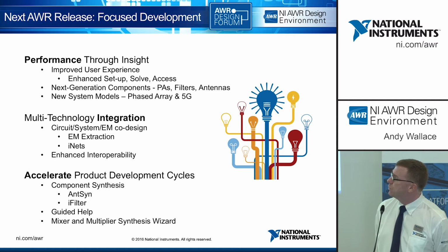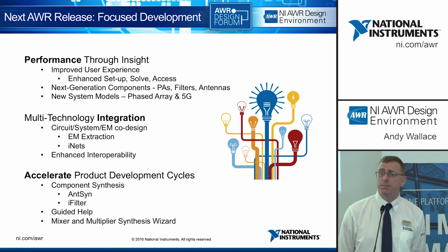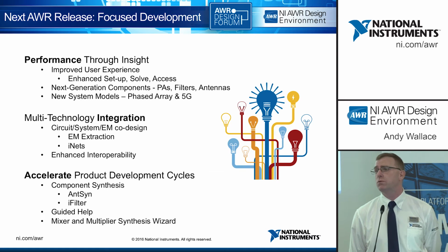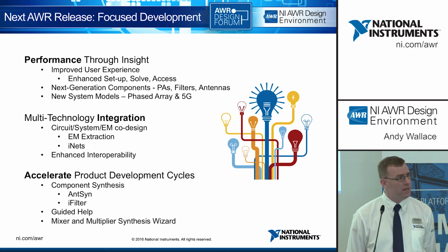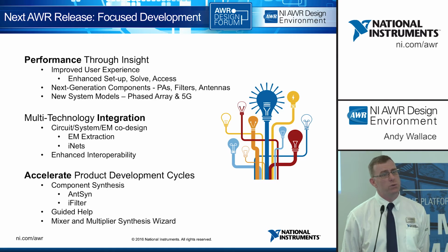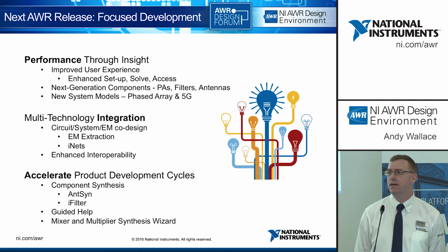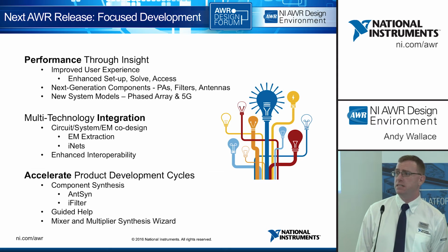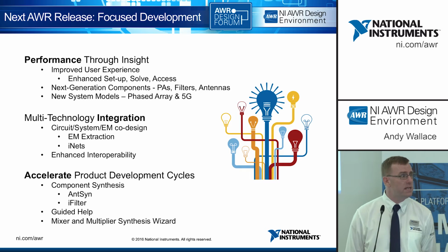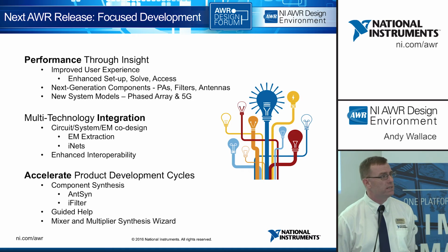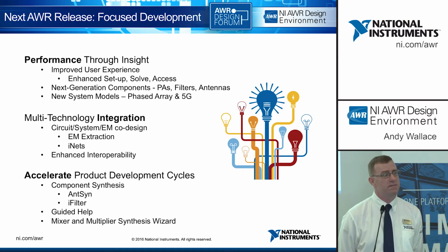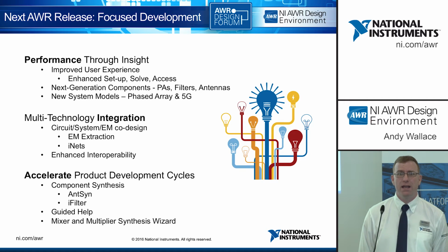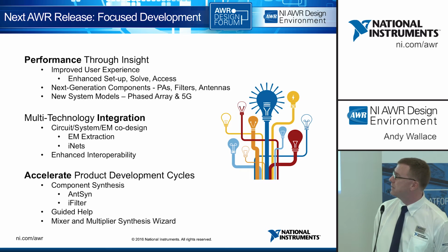Product development cycles, what else have we done? I spoke briefly about Antsyn, but another thing we've evolved is the iFilter tool, a filter synthesis suite that we've had before, and we could do standard filter implementations. But rather than designing the filters, this is synthesis, actually placing zeros at DC, infinite or finite zeros in the transmission characteristics, and synthesizing the filter from there. And again, like the antenna design, that exports into Microwave Office and allows you to simulate the product directly.